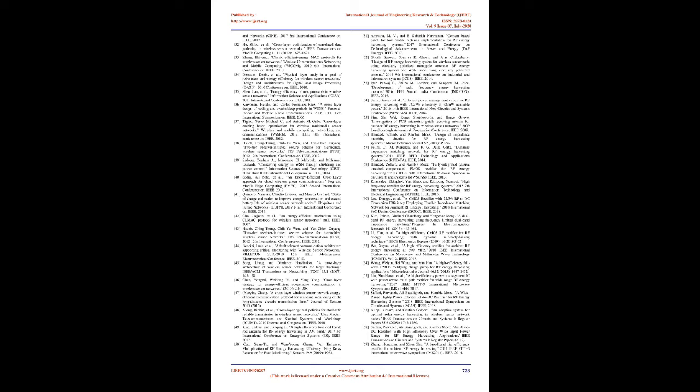Sadiq et al. 2018 proposed a 2.45 GHz reduced power rectifier for generating power from radio frequency, RF, with a 180 degrees hybrid junction. The proposed rectifier has 2 rectifying branches and 2 output ports. The circuit delivers maximum power efficiency of 70% compared to the usual voltage doubler circuit.